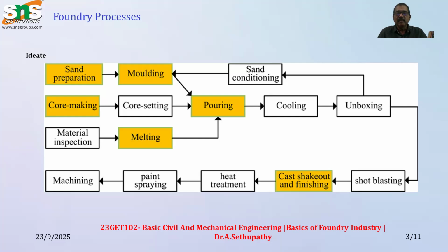The casting comes out with sand sticking to the surface, so the casting needs to be cleaned. We use shot blasting methods to clear the sand on the surface of the casting. Then the casting is shaken out and finished, removing fins and extra projections. If needed, we apply a heat treatment process, which gives the castings stress relief, machinability, and hardness.